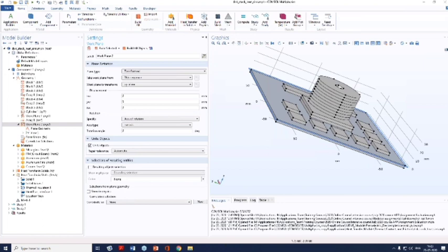Someone has posted an error: I got the following error, there are 7099 void equations for variable so and so. Please check that you have the complete physics setup properly. For example, first of all, you should have the potential constant given in your model, or temperature constant if you are solving for the Joule heating problem. At the same time, you should have the meshing done completely for the entire model.